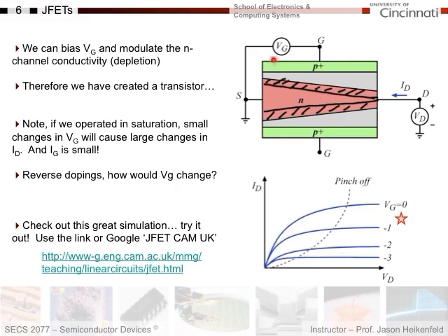This is a type of transistor which is normally on, meaning if you don't apply a voltage at the gate, it has current flow, and you have to apply a voltage to turn it off. Okay? And you can see here are the pinch off voltages at which all of these start to level off and saturate.